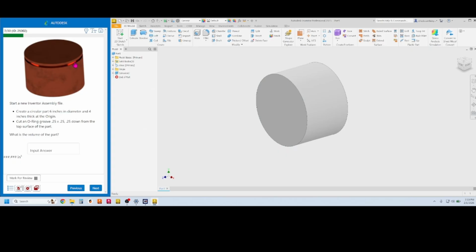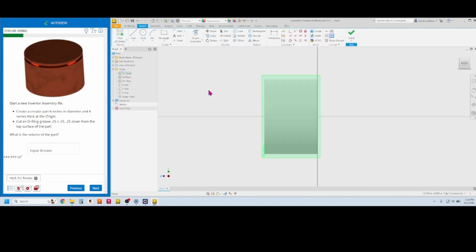that's this part. Now, how do you cut that groove in there? Well, we're going to have to do a revolve to get that cut on there. Some people might try and draw a circle and then a smaller thing and extrude it, and then a bigger one. Now, we're going to cut that with a groove. So we are going to start another sketch. The sketch we start needs to be cutting through this thing either vertically like that, horizontally like that. Do not use the back plane, doesn't work. It has to be one of these two planes. I'm going to pick the YZ plane, and that's cutting my part.